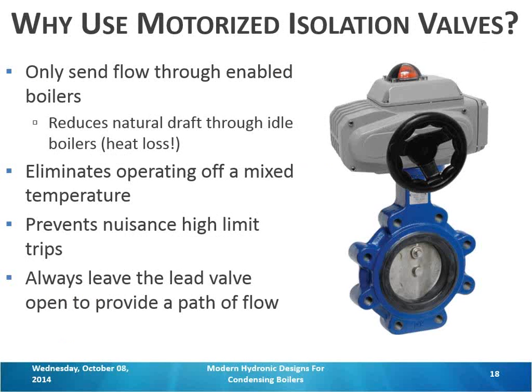And the facilities guy is scratching his head why every single boiler is locked out in the middle of October when they don't need much heat. And that's why: those isolation valves, or the lack of the isolation valves, is causing a mixing temperature. In a 2-boiler plant, you can sometimes get away with it because the effect of mixing is less.